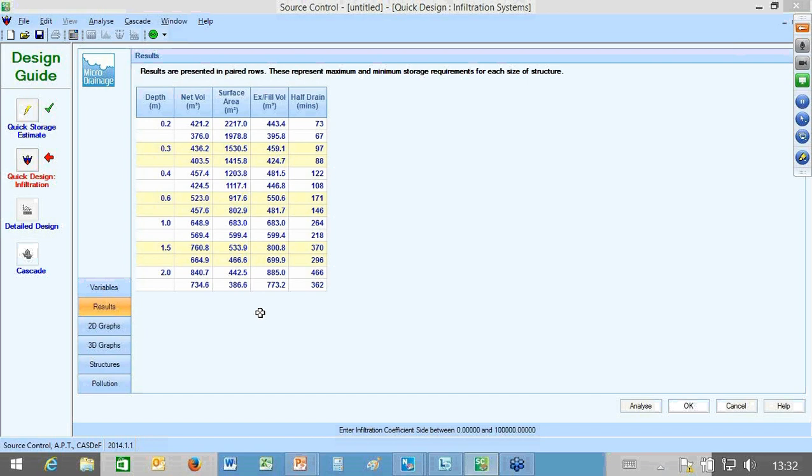Also be aware that we need to have ideally a meter of clearance between the invert level of your structure and the top groundwater level. Okay, so this is to allow the water to infiltrate down and for you not to be adversely affected by high groundwater tables. So that is really the key thing here. So how deep could we put a structure in place? Sometimes the top groundwater table, you could set a datum level there, add a meter to it, and then that's the invert level of your structure.